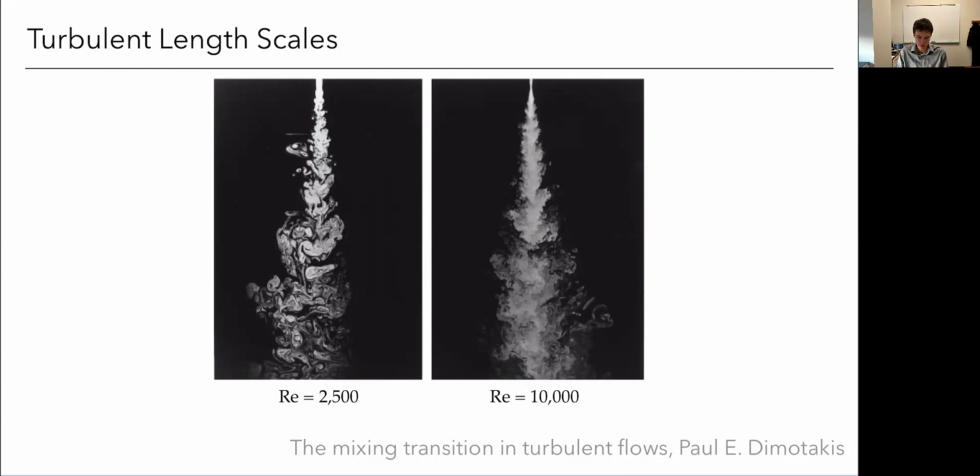in these structures, right? On the left side, I can see these large structures in the fluid, these larger vortices. On the right side, there are still the big structures, but I see a lot of really fine structures. In fact, I can't really see them. If I was to zoom in closer, I would see this type of behavior, but because they're so small, it just looks more foggy, if you will. So these are typical features of turbulence: as we increase the Reynolds number, smaller and smaller scales of turbulence develop. And actually, this is the big challenge of simulating turbulent flows, as we'll see.